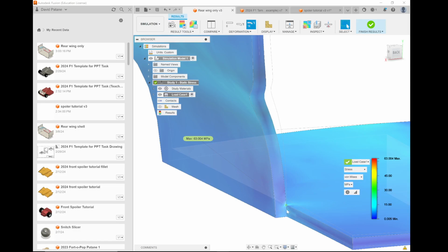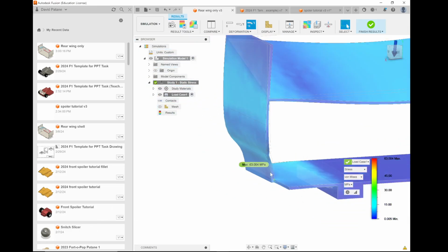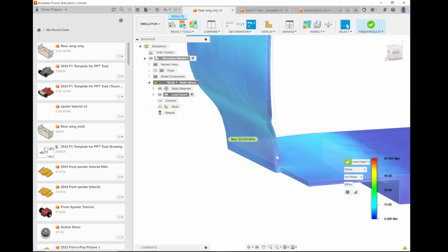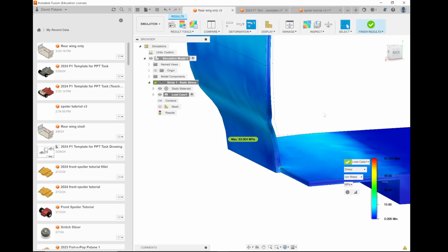This is where a right angle piece is. If you imagine that vibrating, or the force, eventually it's going to start breaking, and that's where the little crack will start growing. So in my design, that's something I would have to consider. The next thing, we said our thing is at least 4 times stronger. So even if we fix this by curving this part, our next problem is our object is way too heavy.